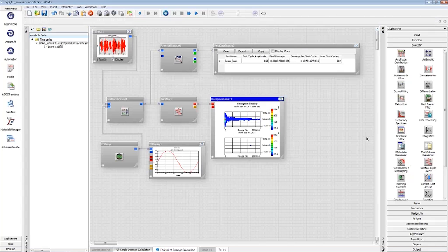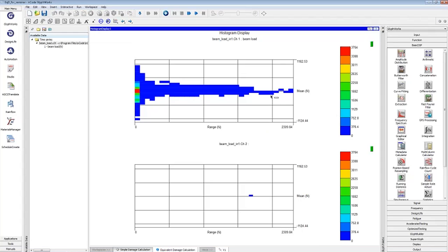So what I want to do now is create a simple extension of this. I want to actually create a block cycle and make this slightly more representative. So we have one cycle, and you can see where this falls in the spectrum of the in-service loading. I'm about 75% of the way up to the maximum one. So I want to pick a couple more amplitudes that fall within this range as well.